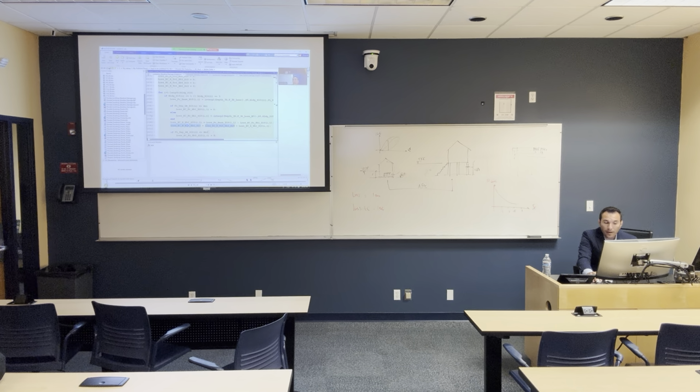And then I'm trying barrier number 2 here. I'm saying if the flood depth measured from the ground elevation is less than 0.4 meter, put 0. But if not, else calculate the flood losses from the 3D surface with elevated components. And I keep doing this for barrier number 3, barrier number 4, barrier number 5 that has a height of 1 meter. And once I'm done, I do else and I write the same code.